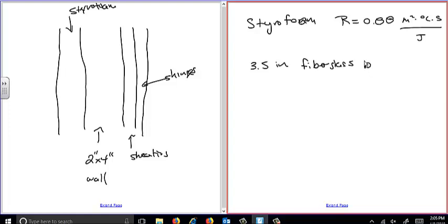So what that is, that's going to be the wall. This 2x4 wall is a 4-inch wall, and we'll put 3.5 inches of insulation in there. The R value is equal to 1.92. Again, you'll have this table, but you'll be able to get this stuff off however I decide to put it together.